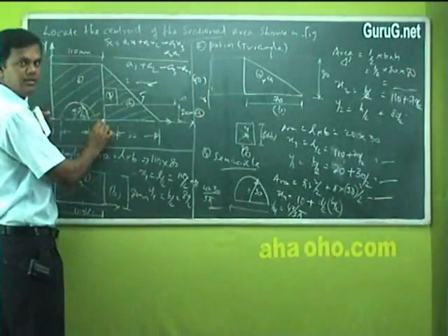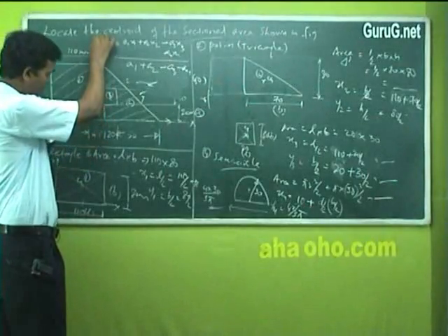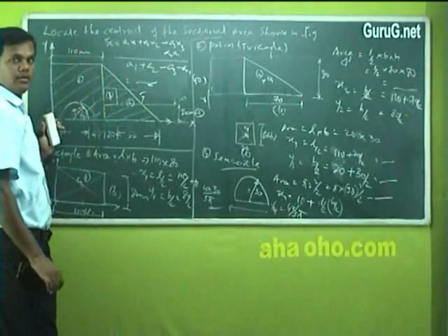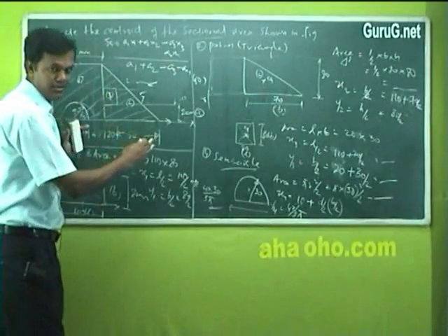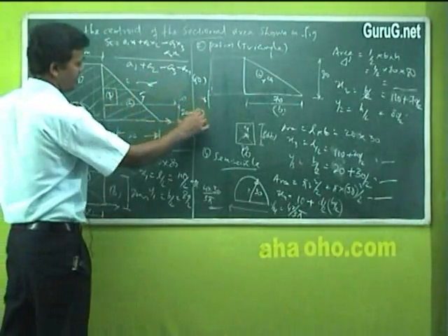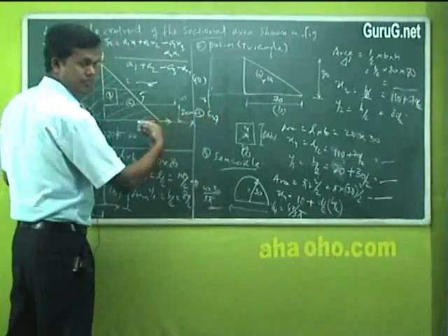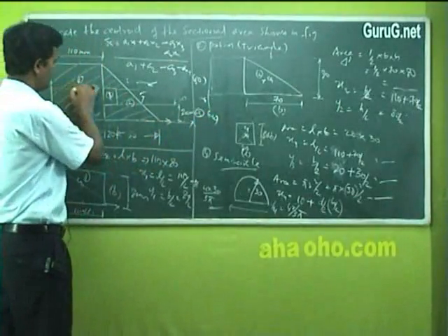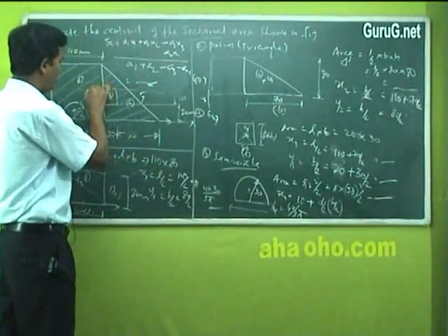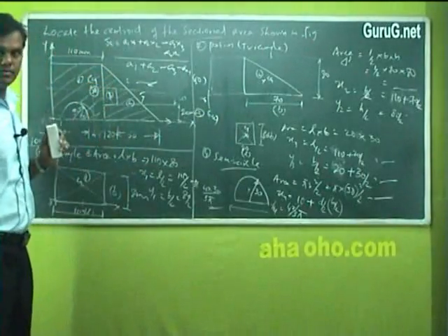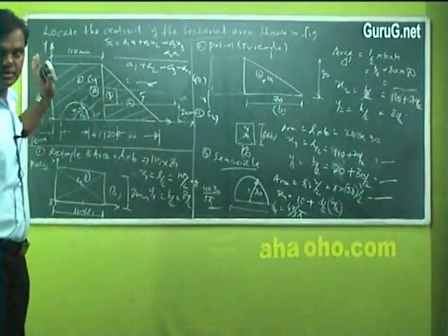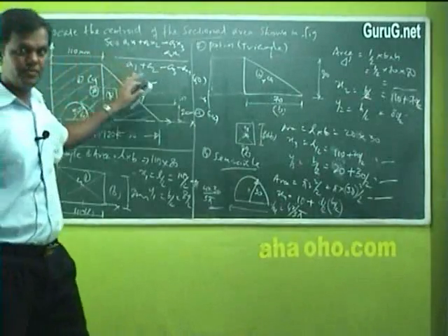From here I have to measure, say scale 50 millimeter. I have to draw a big line, the center of gravity on the x axis side. And y bar, suppose I get a value of 40. I have to draw this. Finally indicate a big round CG, with my x bar line. This is the procedure followed for every problem.